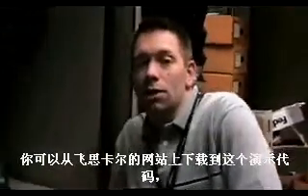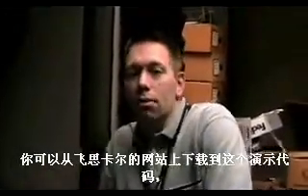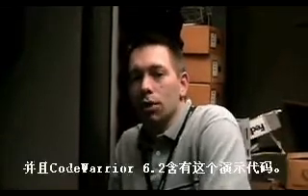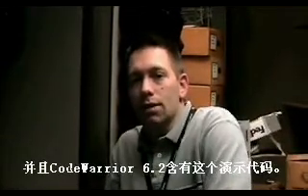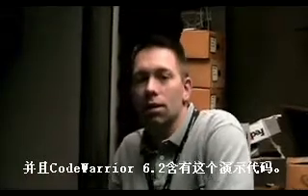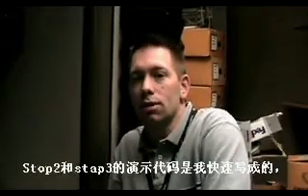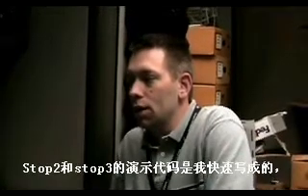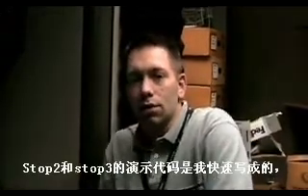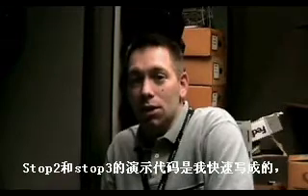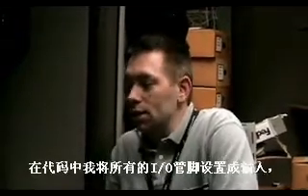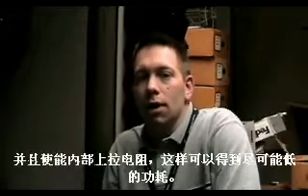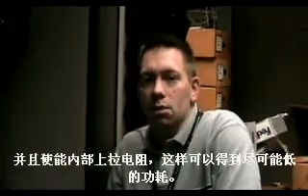To get all this code, you can download the QE Low Power Lab from the web, or it's also available within CodeWarrior 6.2. You just download that. It is part of the evaluation board demos. The stop 2 and stop 3 code was really just kind of a quick thing that I jotted down. To let you know what I did though, I set all the IOs up as inputs with pull-ups enabled, and that's going to allow me to get the lowest power possible.